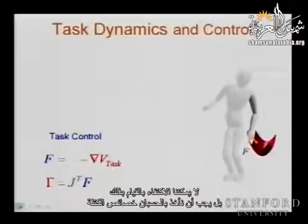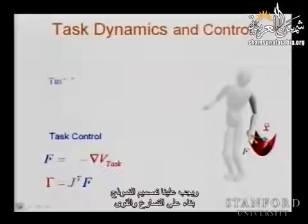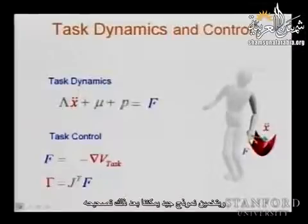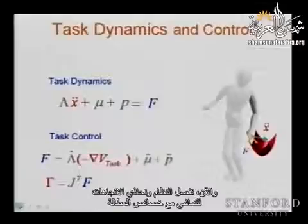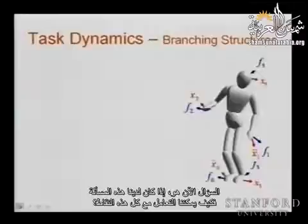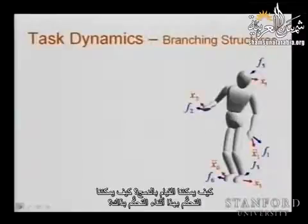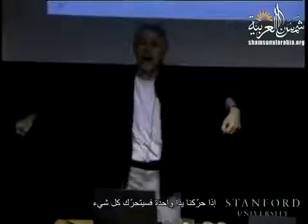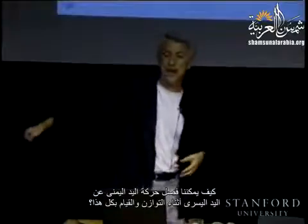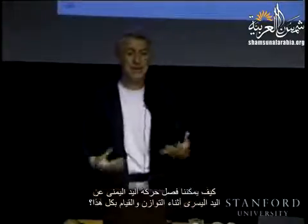That should work. We said we cannot just do it like this. We need to account for the mass properties. We need to establish the model between acceleration and forces, and by having a good estimate of this model, we can go and correct this, and now we decouple the system and we align the directions to follow the inertial properties. Now the question is, if we go to this problem, how do you deal with all these points? How do you combine? How do you control this while you're controlling this? If you move one arm, everything else is going to move. How do you decouple the motion of the right arm from the left arm while balancing and doing all these things?